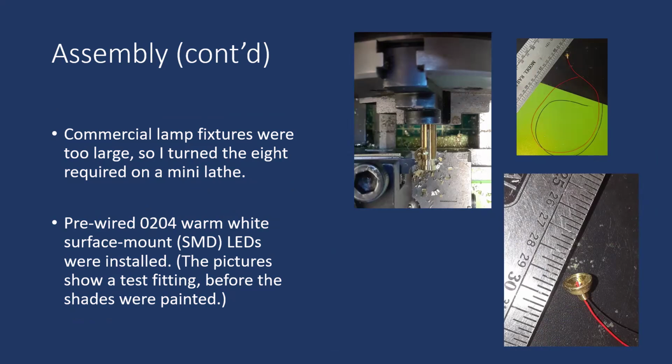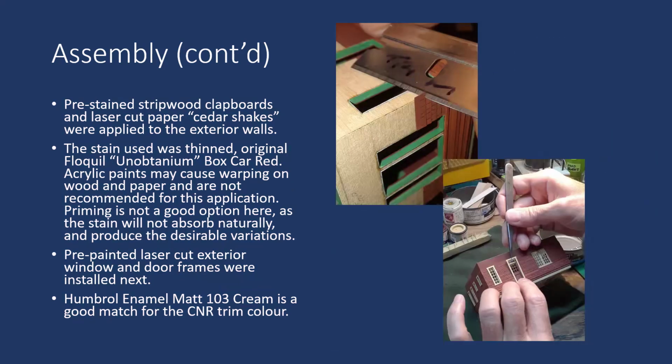Commercial lamp fixtures were too large, so I turned the 8 required on a mini lathe. Pre-wired 0204 warm white surface mount or SMD LEDs were installed. The pictures show a test fitting before the shades were painted.